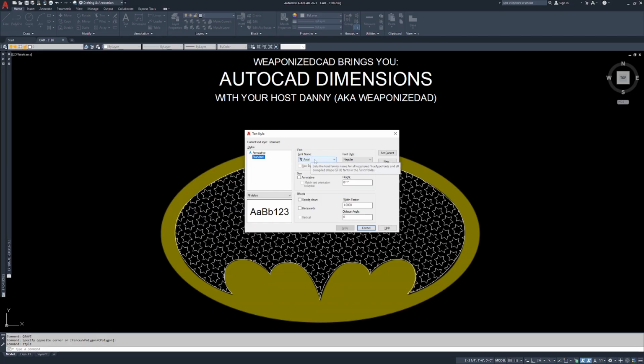All I want to look at right now is the font name as Arial. I need to set it to annotative. Paper space text height typically is 1/8 of an inch. And we leave everything else alone. Actually, that's the standard text style. Let's check the annotative text style.